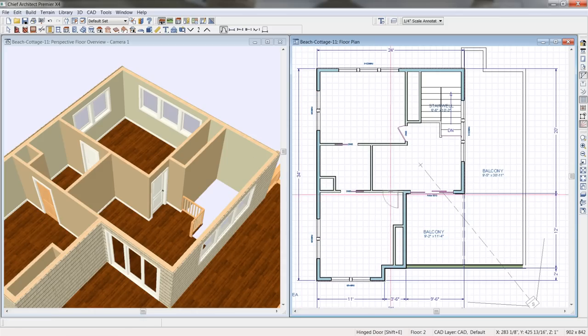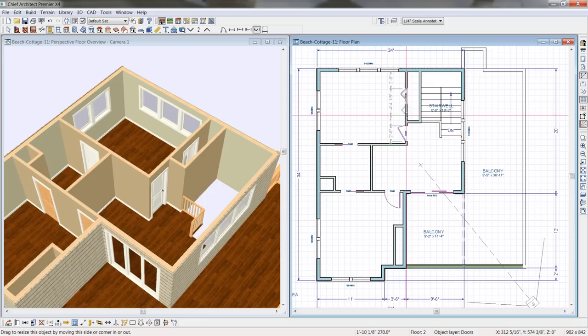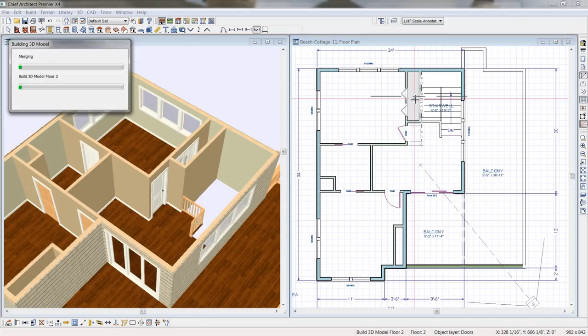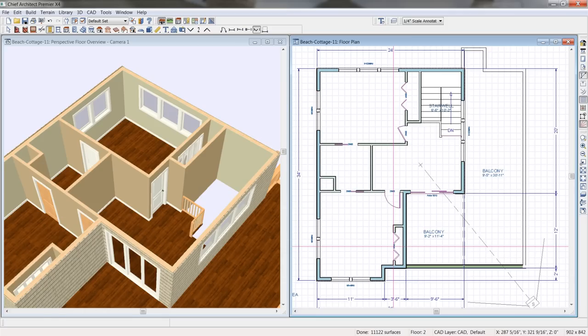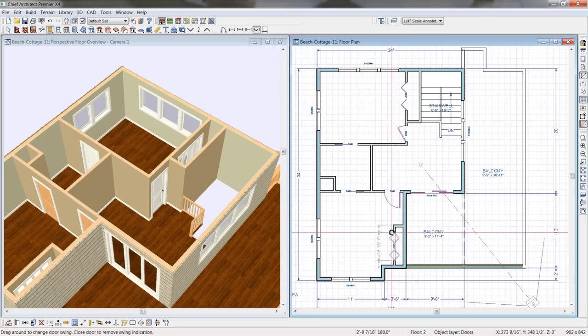And we'll add one more door in here. And then we'll add a couple of bifold doors for the closet. Let's go ahead and make that a little bit larger door. Use the center button. Center it on the room. I'm going to hit Control C for copy and then Control V for paste. Paste that over here. Let's go ahead and flip those doors out.